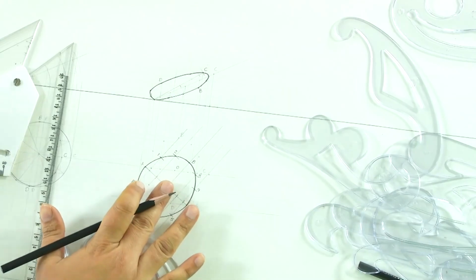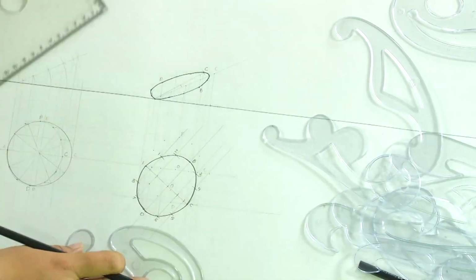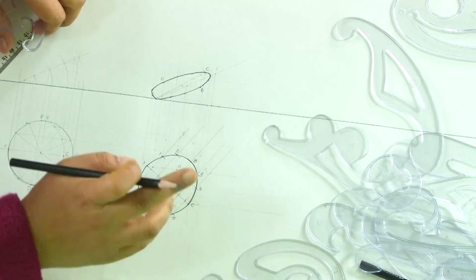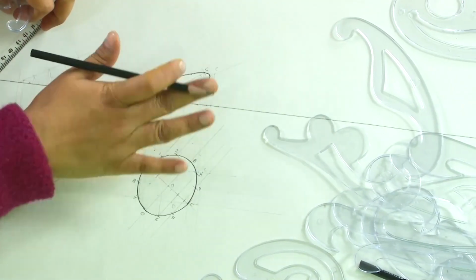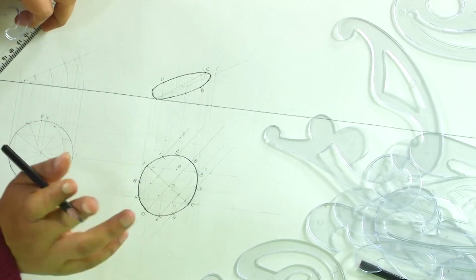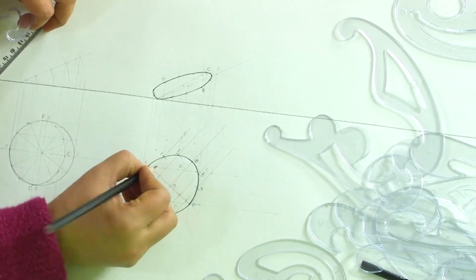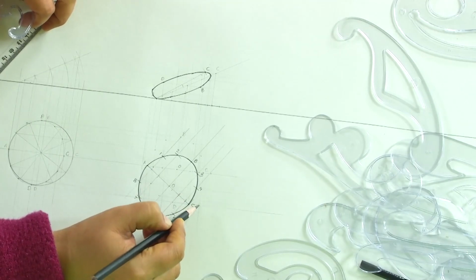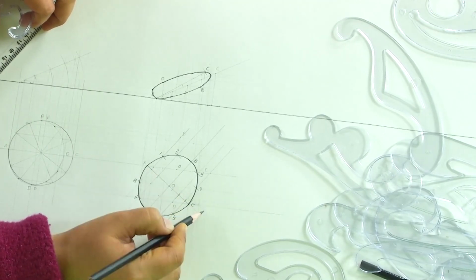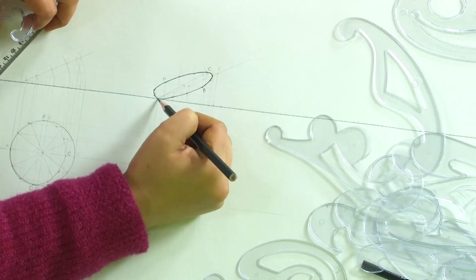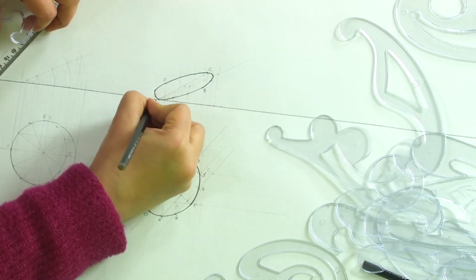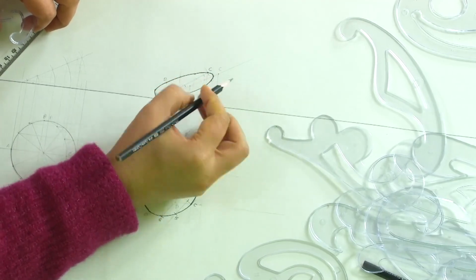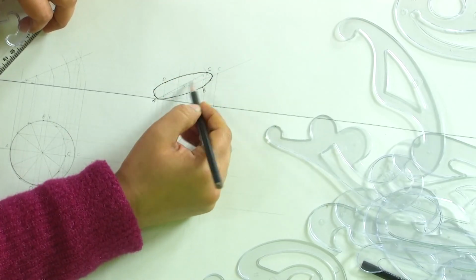This is the projection of this circle where the given condition is that this diagonal AC makes an angle of 30 degree with VP and 30 degree with HP, and you have to remember that we will not be seeing the true angle anywhere. So, if you see, this AC is slightly off from this line which we had drawn as 30 degrees, and here also this AC, this is A, this AC is slightly off in terms of angle from the line which we had drawn as 30 degrees.